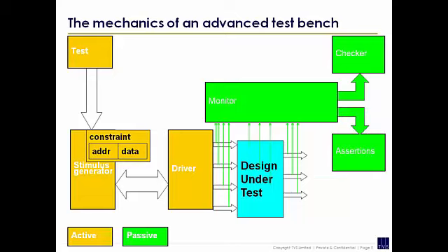Okay, and assertions as well. So you can pass these monitors to assertions. So these assertions may be embedded, and maybe that's what you do in the VHDL. You embed it in the design. So you can put the assertions directly into the VHDL or into the Verilog, or you can have them hanging off the monitors. Okay, and quite often these will be doing protocol checks. It's just obeying the protocol.